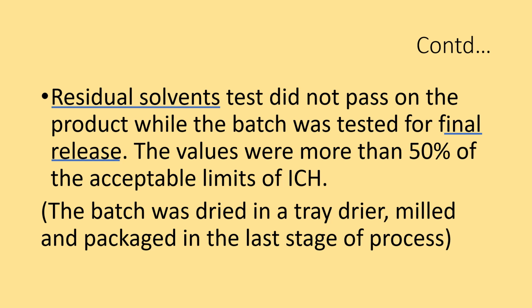Initially, the laboratory OOS investigation should include checking the validity of the standards, preparation of standards, including the weights taken for the standards for preparation, glassware used, and compliance to system suitability parameters. Since the residual solvents are being analyzed by using a headspace analyzer, the investigation should focus on the potential leaks in the headspace system. All these parameters have to be checked and documented with details of what exactly the observations were.